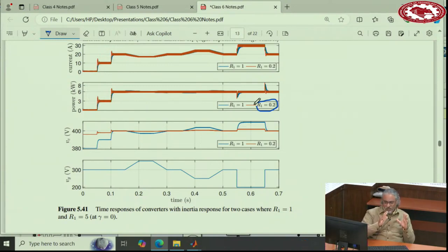And again, in synchronous machines you cannot do it, because it comes from the winding of the system; there is no way to reduce that inductance or reactance. But here it is a control parameter. If you decrease it, it means that you have a smaller reactance between them, so the responses become faster. Look at this, but some oscillations appear in the response, at the transients.